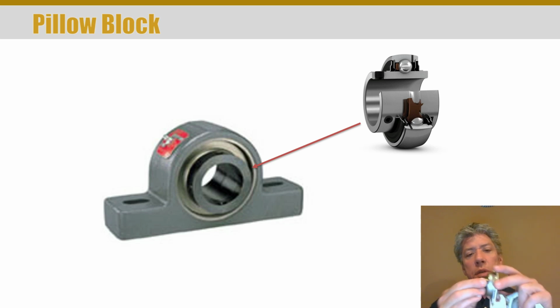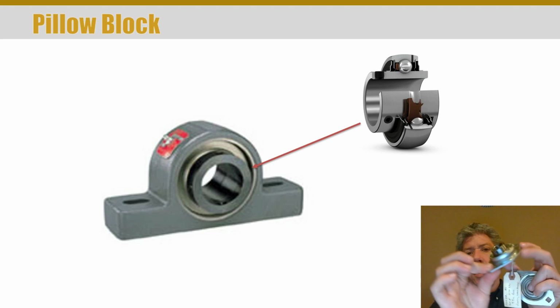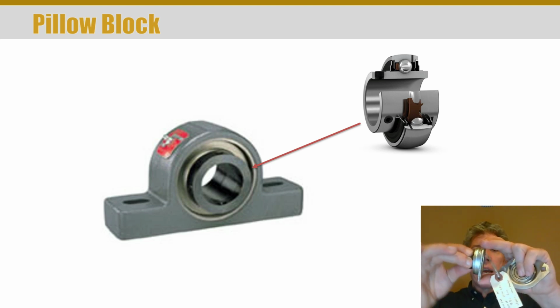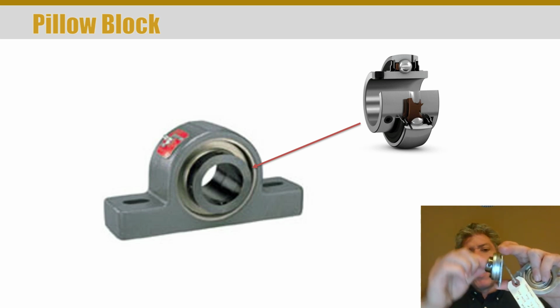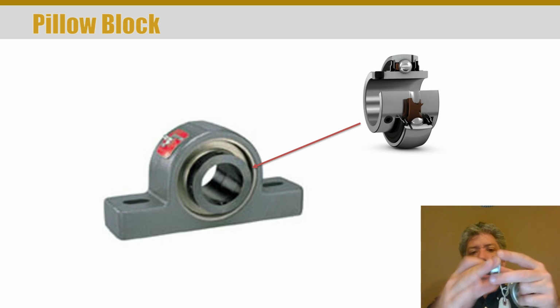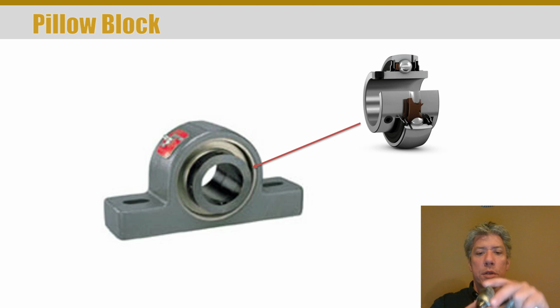So anyway, this one you can really see it. You've got this fairly cheap pressed steel or sheet metal housing that the bearing insert rides in. You can see how that bearing insert pivots around so that you can clamp this to the frame or bolt it to the frame, but then the shaft in it has play, and you can align it across a frame that is welded and so not very precise. Of course, these are much cheaper than the more industrial pillow block type bearing that I showed you, and I thought I had another pillow block. I guess I don't.